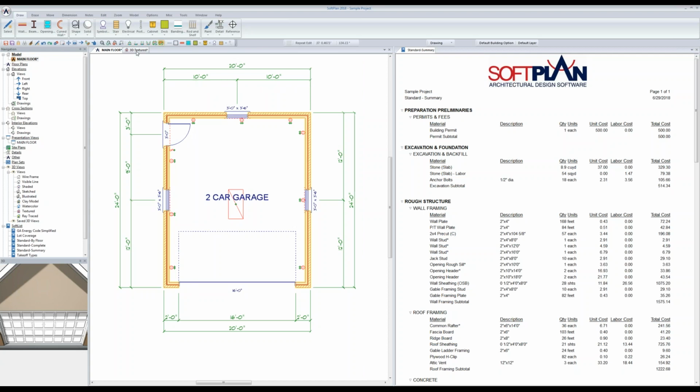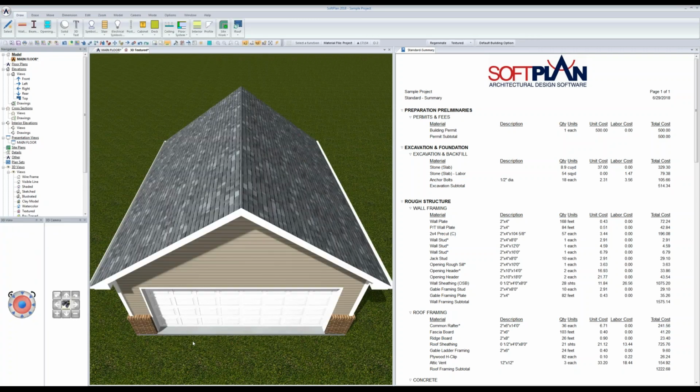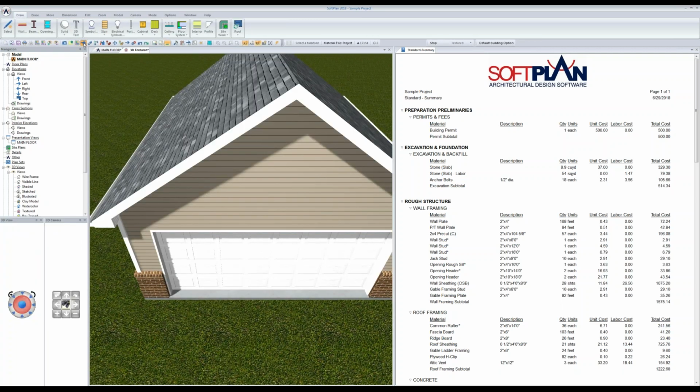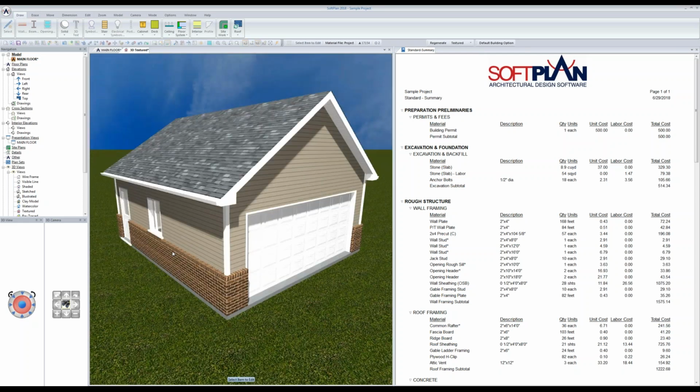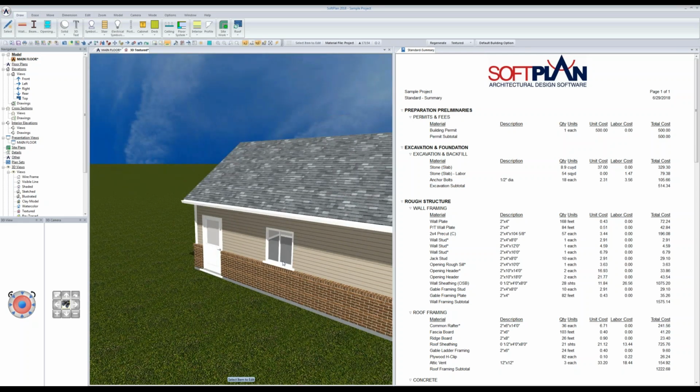Let's bring up a 3D tab again. I'm going to add a little bit of information to the openings. First and foremost, there is a sill that gets added. A sill gets added to any wall that has a brick, or a brick in its definition. In this case, my brick is below the window itself, so I technically don't need this sill.